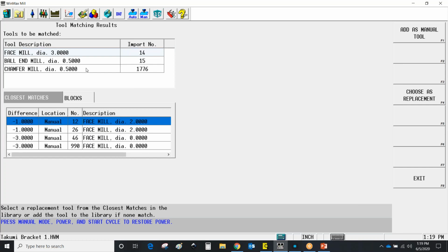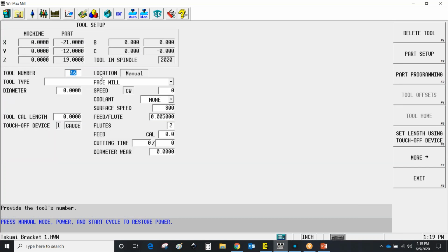we didn't give it a diameter and so forth. That's the other thing. When I created that tool, sorry, I skipped over that. Once the tool has been created from the database, now we start to give it its independent information. Now the 3-inch diameter, it knows that it can calculate an RPM for us now. It can calculate or use the surface footage, chip load, number of teeth, all of that.